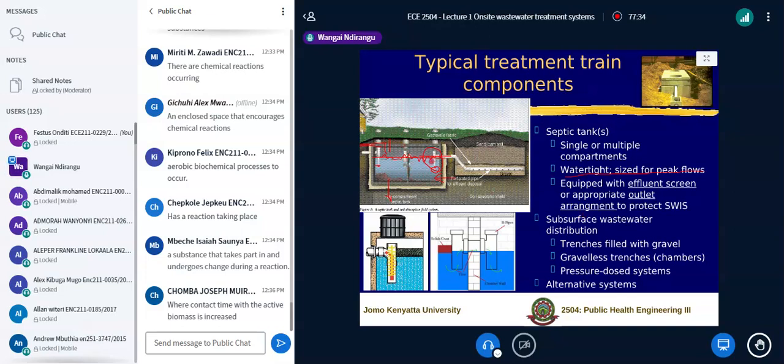The third thing is that we have an inspection chamber. Very important, the only way you can see what is going on in there is through the inspection chamber, or what you call the manhole. Another very important thing is something we call the plug flow conditions, the length to width ratio.